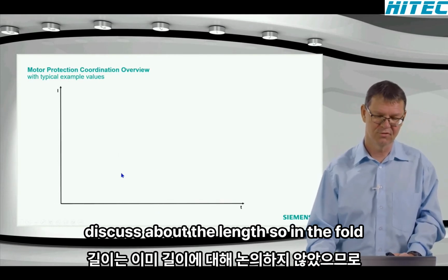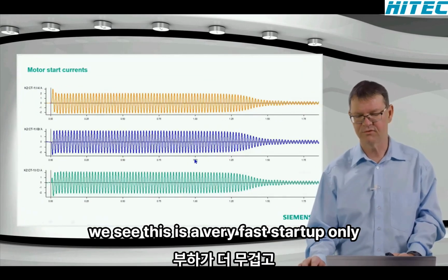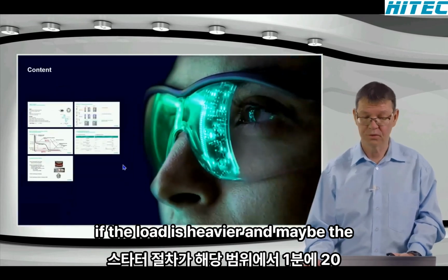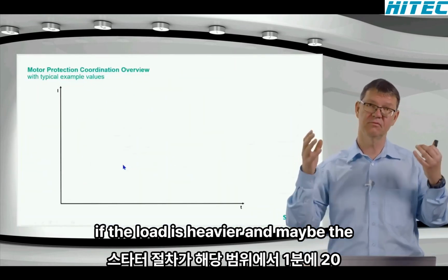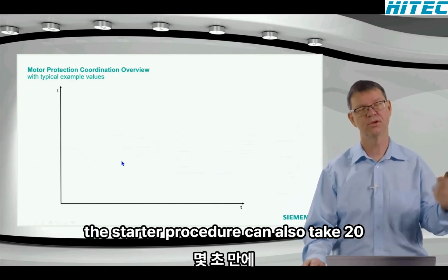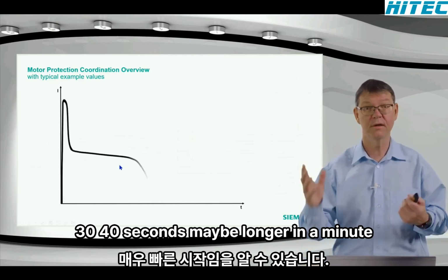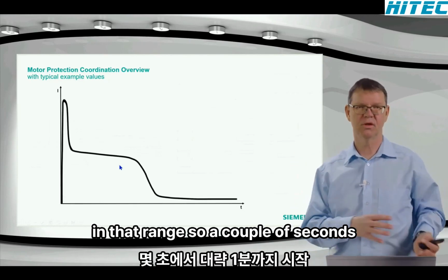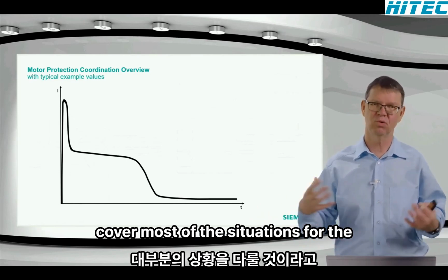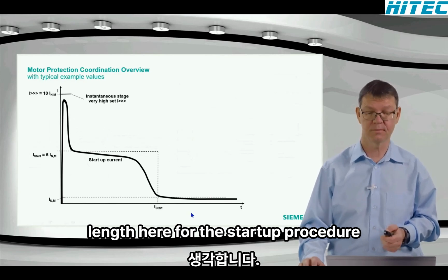So in the fault record here before, does this come back? We see this is a very fast startup, only a couple of seconds here. If the load is heavier and maybe the voltage is not the nominal voltage, then the startup procedure can also take 20, 30, 40 seconds, maybe longer, even a minute, in that range. So a couple of seconds until roughly a minute, I think, will cover most of the situations for the length here for the startup procedure.